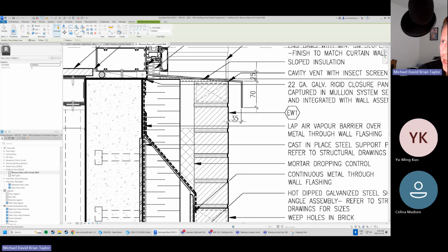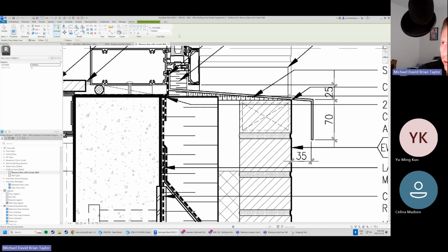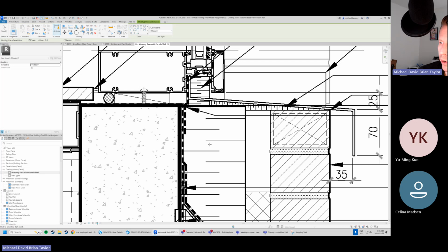Okay, but we're drawing a line. So if I want a little membrane here, if you remember from last class, we did do a kind of brief introduction to how to create new line types. And new line types are going to be effective for us here because we don't really have a way to draw a membrane type effectively. So for us, what we can do is start with hidden here, and I'll show you what that looks like. It's probably not going to be the right thickness.